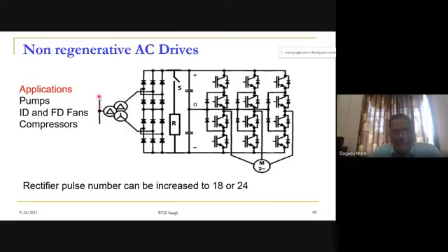So here harmonics will be reduced. That is the benefit of the 12 pulse rectifier. So here we have seen that with the help of this particular transformer configuration, the fifth and seventh predominant harmonics are completely eliminated, and the dominant harmonics are the 11th and 13th. So that is a benefit we can get with this configuration.